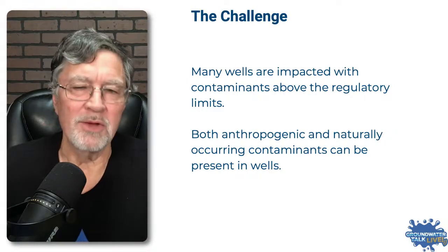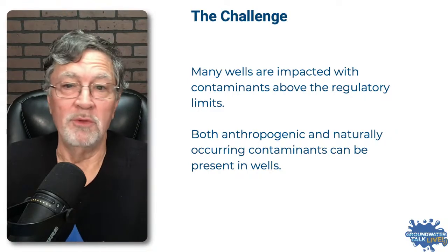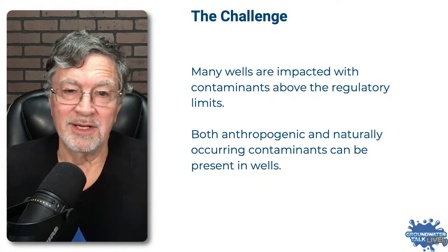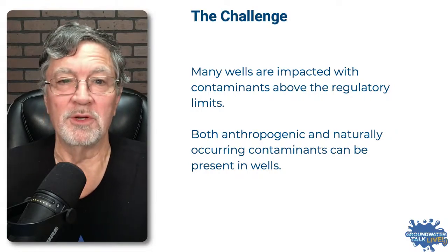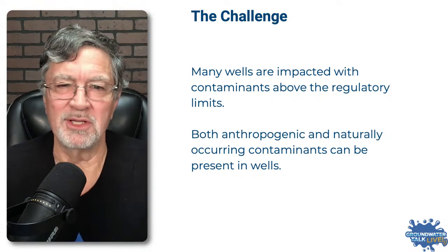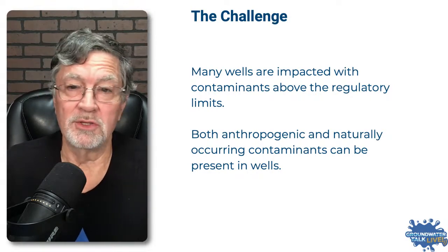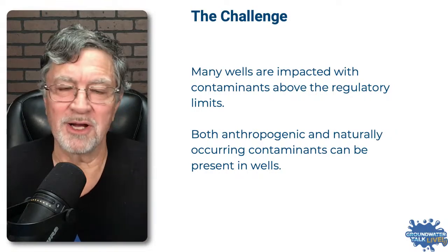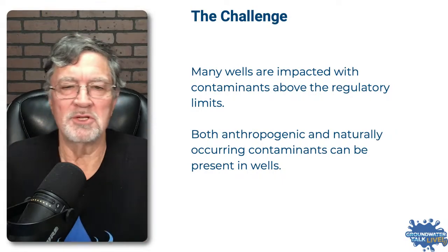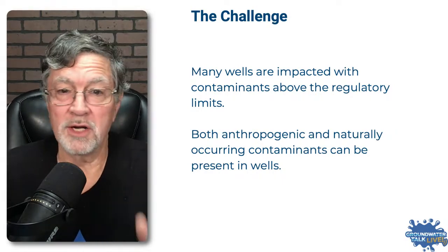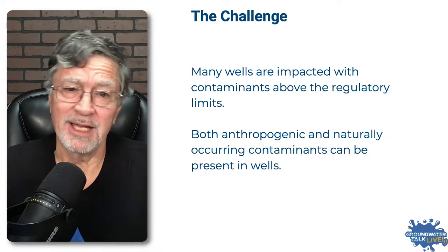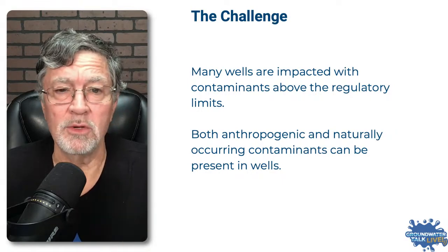I did mention that many wells are impacted with contaminants above the regulatory limits. The MCLs is usually what we're using. Different states have their own, like California, for instance, has their own MCLs that may or may not match the US EPA MCLs. So when I talk about regulatory limits, I'm mainly talking about MCLs, whether it's state or federal MCLs. So a lot of wells out there, water supply wells that are supplying drinking water to folks, basically have contaminants in them that they need to deal with.